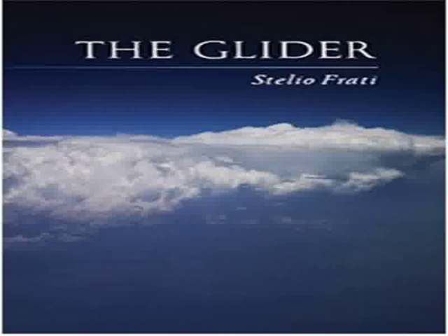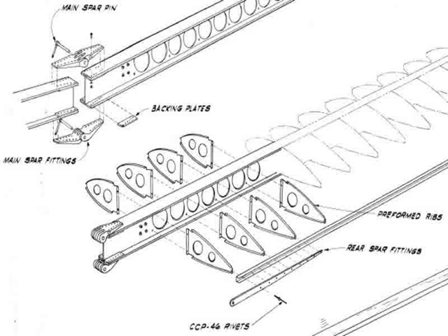Lots of relevant information. With the basic glider research done, we looked at the wing structure, and we found, if you can see the picture on the screen now, that there's a main load-bearing spar that goes through the wing, and then there's smaller spars fore and aft that are not load-bearing as such, but they're there for the support of the ribs, and they offer support for when the wing is skinned, as it were. From the research, we saw that it had to be very light, but keep that strength. So, if you can see our design, that's what we've gone for.